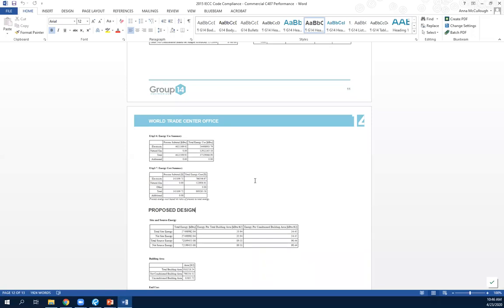It was like a 45-year payback, I want to say. So what we do is we say there's a way to model the actual visible transmittance of the glazing depending on the solar irradiation hitting that panel of glass. And the energy model will calculate all of that for you.